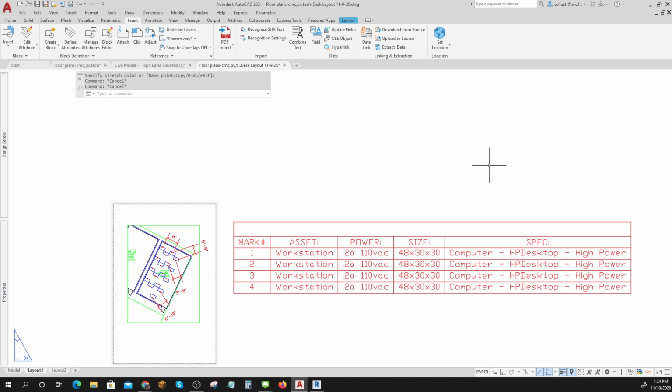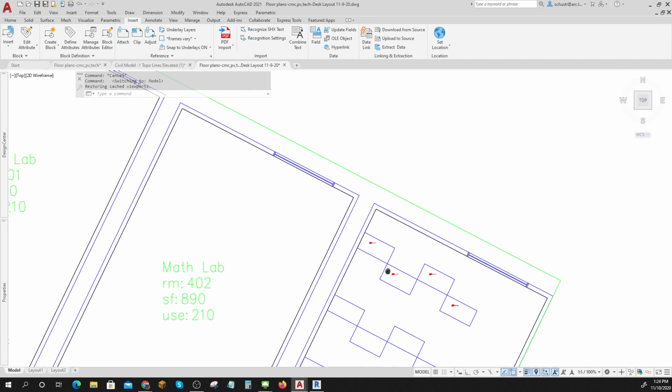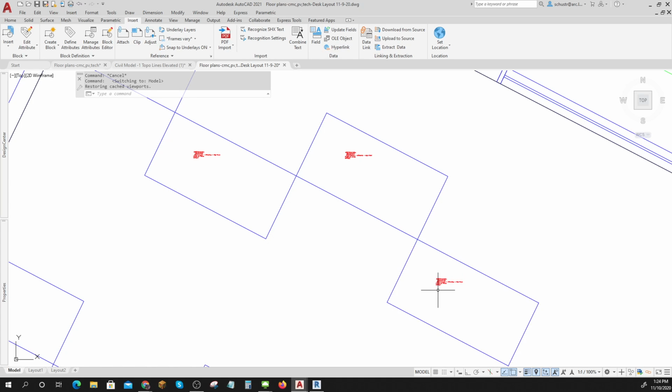What attributes do I put down? It depends on who I'm talking to. In this case, the people that want to know about moving our equipment want to know this stuff. So I'll make attributes for the block. And then I can just put the block in and bing, bing, bing, bing, bing, away it goes. And I can actually count them up. There are other ways to make these lists of materials, but that's how you do one. Isn't that cool? So that's a list of materials.